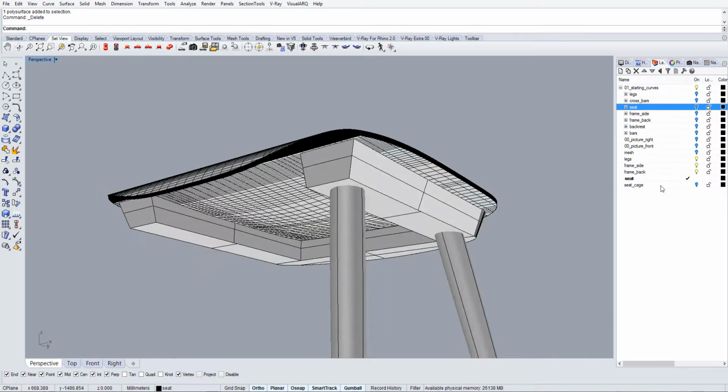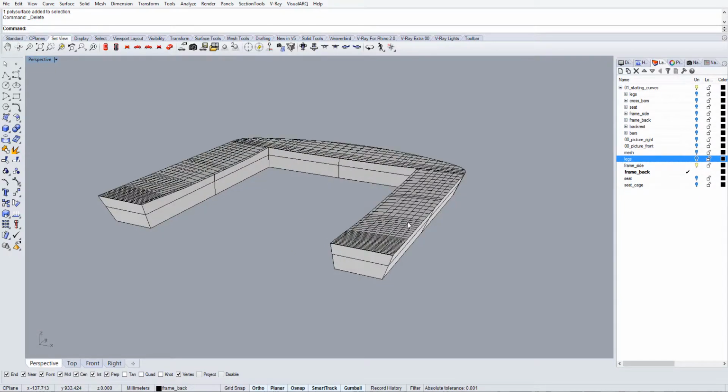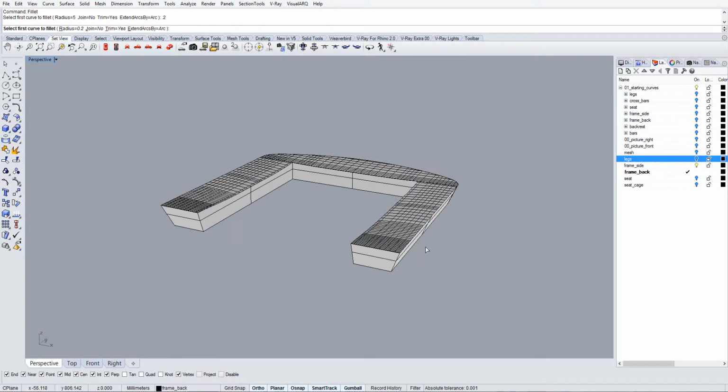Okay, we can actually turn this off. And now with the frame, we can use fillet by 0.2 millimeters. And we can do this, we don't have to do it with the sweep, as we're gonna use just box mapping for that. Okay, it's fillet edge, not fillet. Fillet edge. Okay. Fillet edge 0.2. Now it's correct.